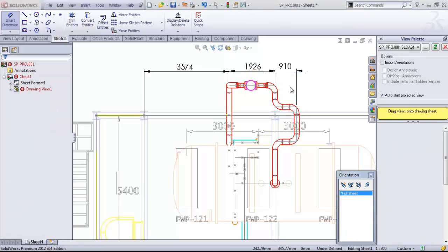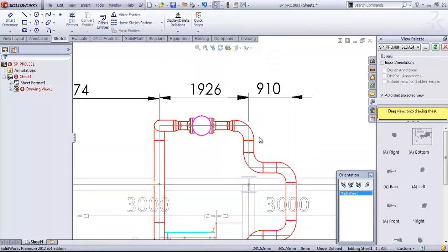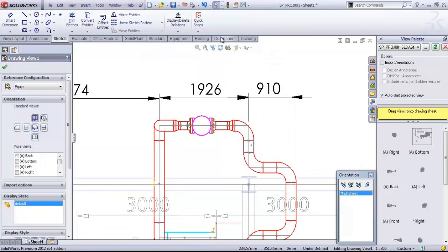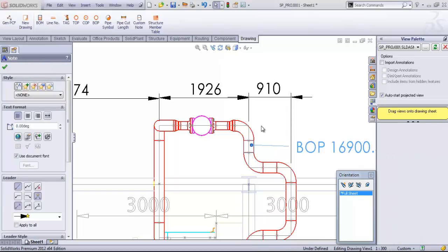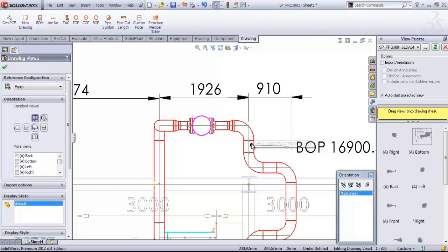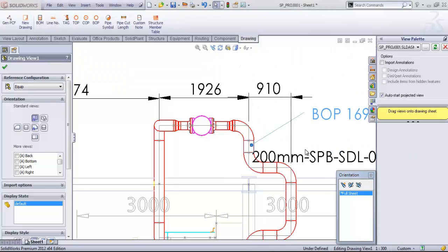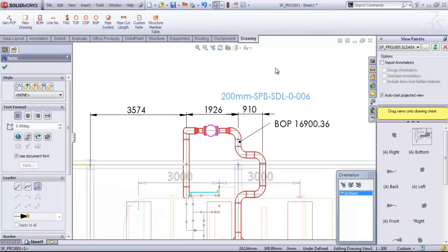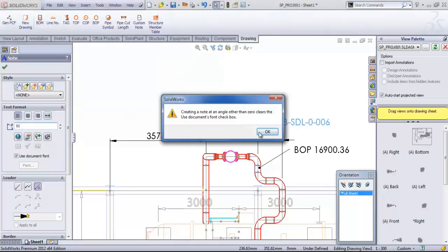Now with Solidplant, we can select, for example, the section of a pipe. So we select this one, and then press the button of pipe for the elevation referred to the soil. Then click on another one, and click on line number. We have the detailed information of the pipe. We can change the direction of the node if we want to, so we do it.